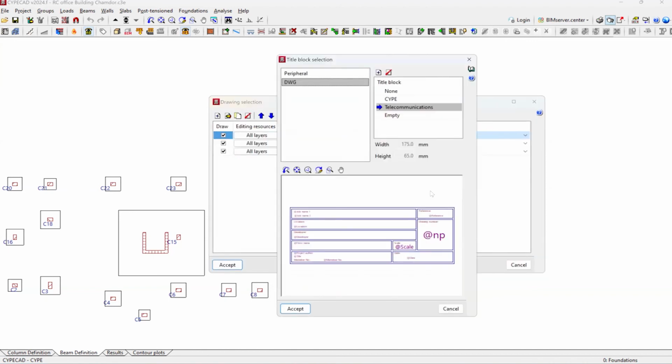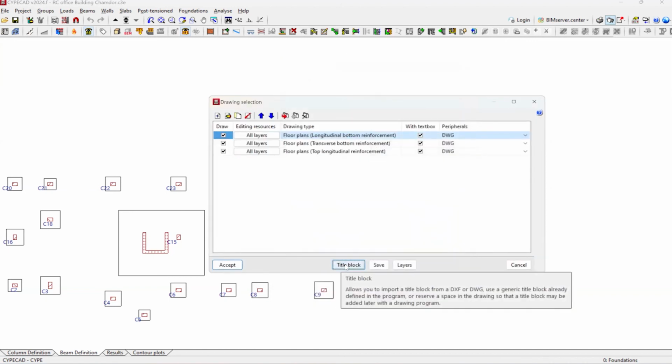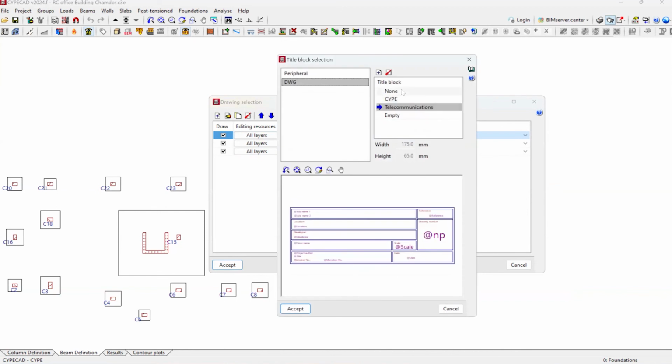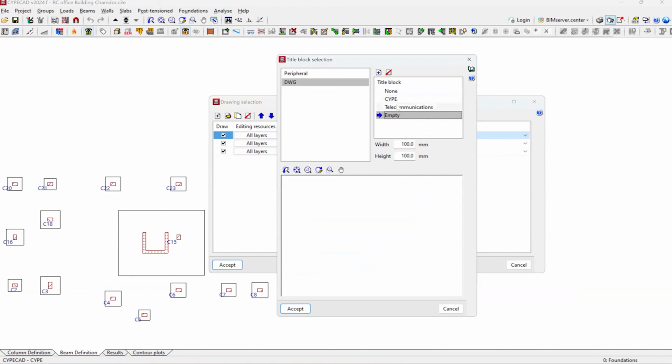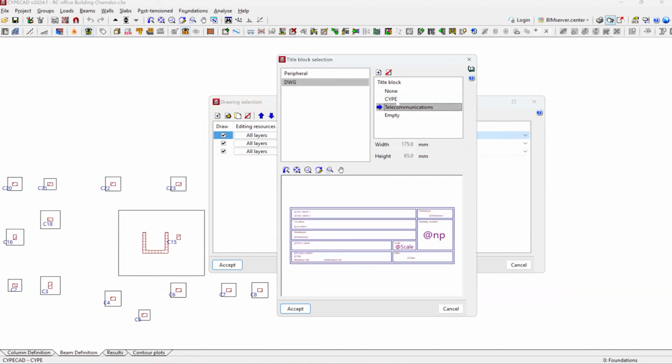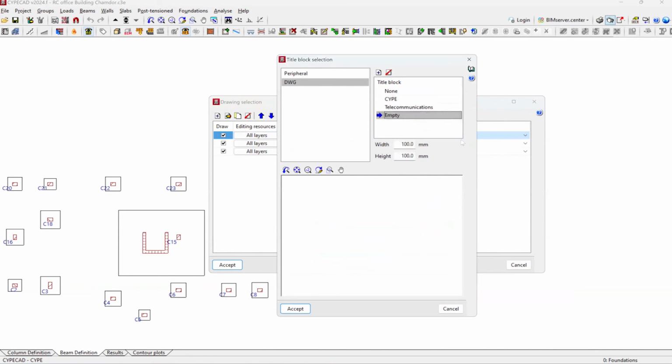Then here you've got the option to choose the type of title block that you would want to put on your construction sheet. For example, for this one here, you've got the site one, there are 2 options that you can choose, but the one that says empty, if you have already done your own title block as the office, because each and every office in South Africa, they would have the engineers, they would have its own title block.